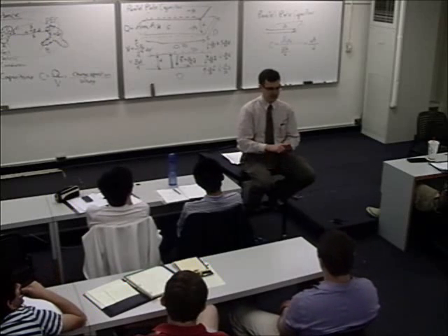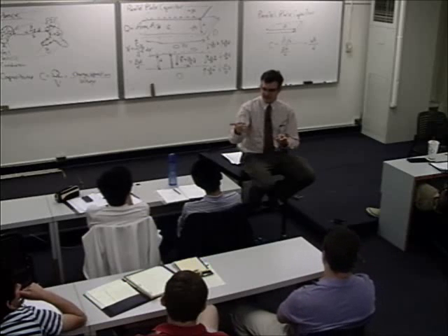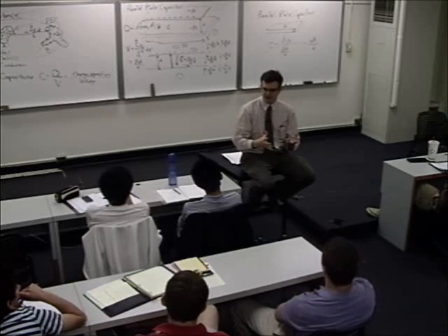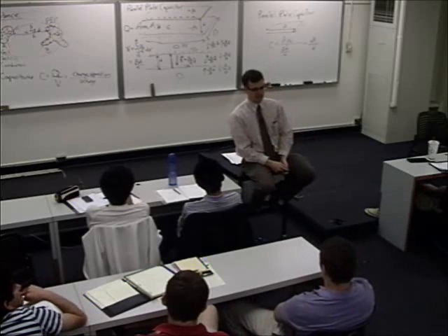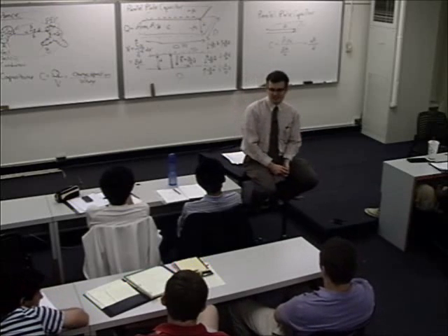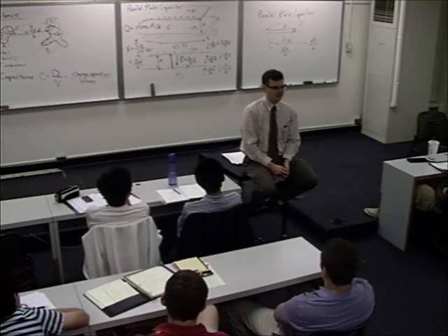Yeah, we got to change the epsilon. We got to decrease the distance d, or find a way to increase the area. So here are the different ways that we electrical engineers realize this in practice. First of all, the easiest thing to do, because these things are made out of paper, you can only get so thin. And what's more, paper is mostly air. Air is a terrible dielectric. So you don't really want to make super, super thin paper.